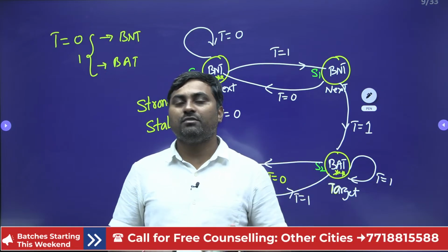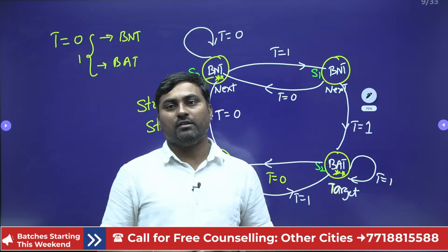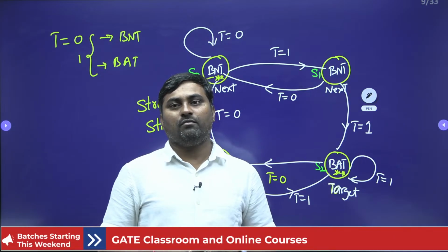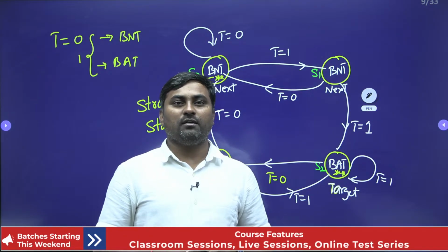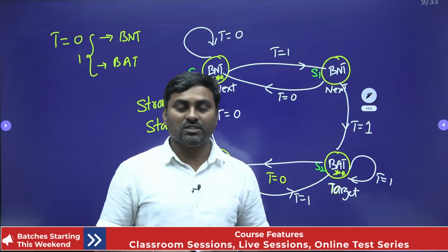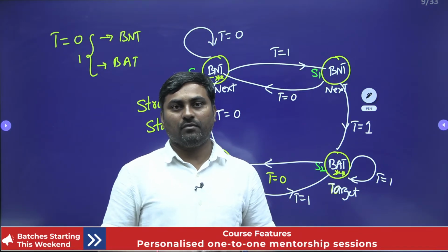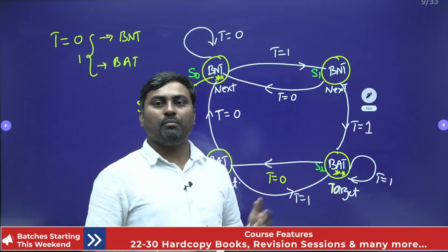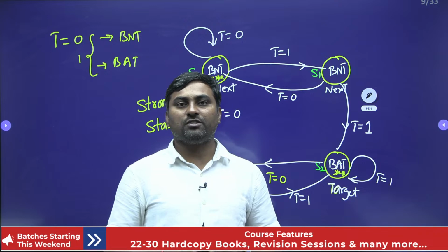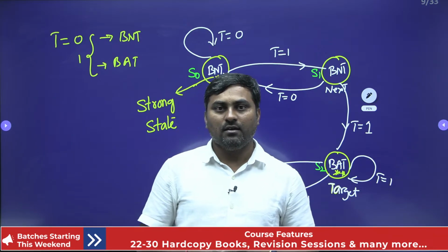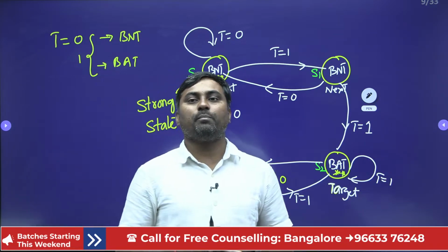So the accuracy of the prediction rate is more than 85%, 85 to 90% it is giving. So in practical cases we are implementing dynamic prediction mechanism to deal with branch types like conditional hazards or conditional dependencies, right? The 4-state machine, the 2 flip-flops. So 2 flip-flops are enough to implement this one. That will decide which instruction to be fetched in the next cycle. I hope you understand the concepts. So this is how we deal with the control dependency problems.